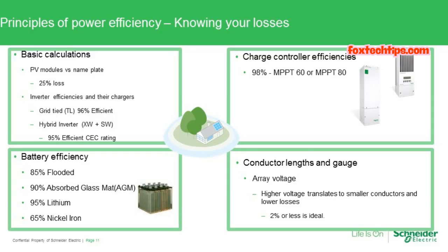And I've been doing this for about 5 years, and that's a very fair number when speaking on average to people from San Diego, Texas, through the Southeast, up through Maine, Vermont, even the Midwest, and especially here in Washington State. I've mentioned my personal system, so I've got a 10 kW array, and typically I'll see 7.2 to 7.8 kW. Even on a nice summer's day where it's maybe 80 degrees Fahrenheit outside, you just don't get what you expect if you were to take the nameplate rating, which is really those standard test conditions where the panels are kept cool and the lighting is perfect.